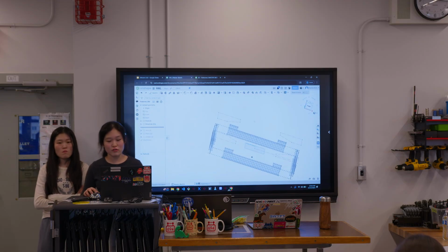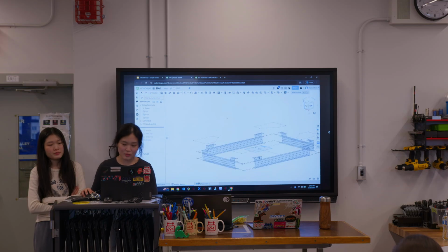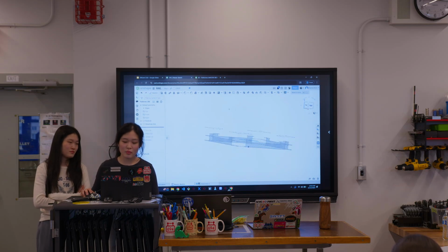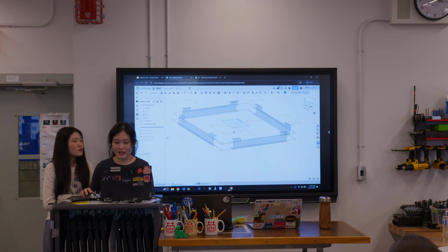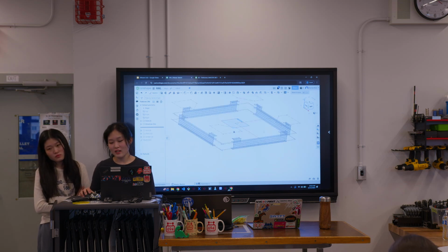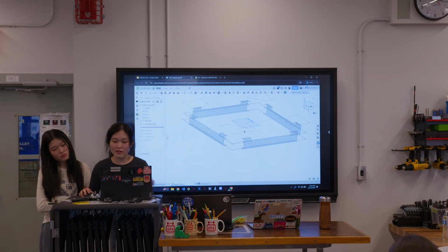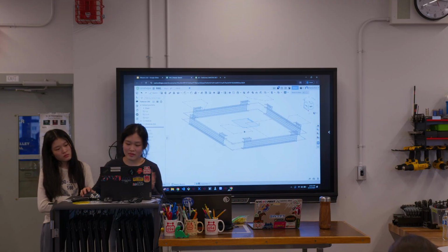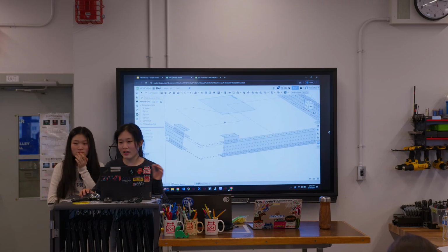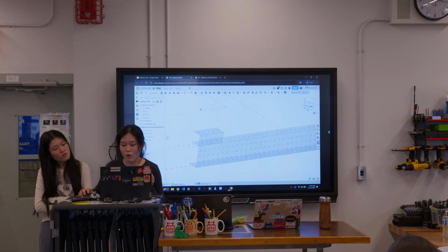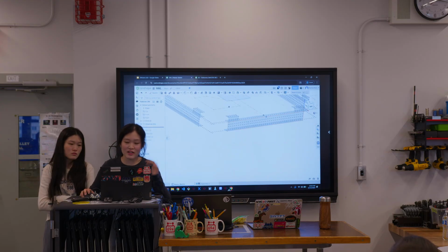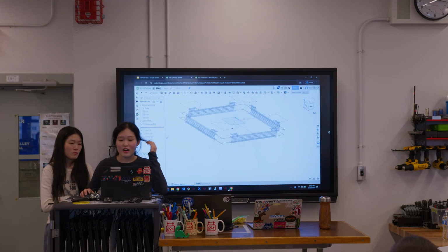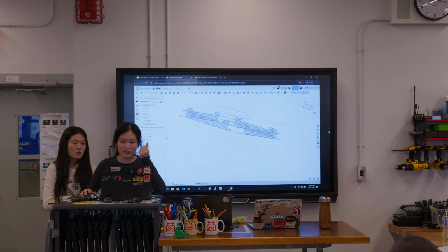The reason why the drivetrain is obviously very important, and one of the most important parts of a master sketch, is because you have a lot of things that are going to go on your drivetrain. The majority of the stuff is going to interact at least partly with the drivetrain because it's being mounted onto it or interacts in some other manner. And if one small thing, like half an inch, is off for the holes, everything won't line up, which is why it's very important to have a very accurate drivetrain sketch, which is why I'm showing this as an example.